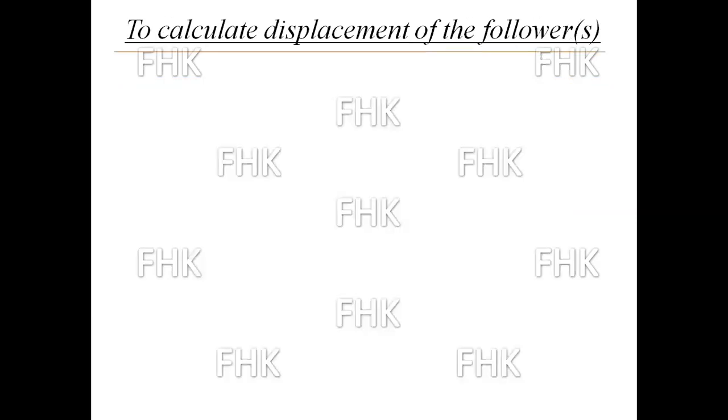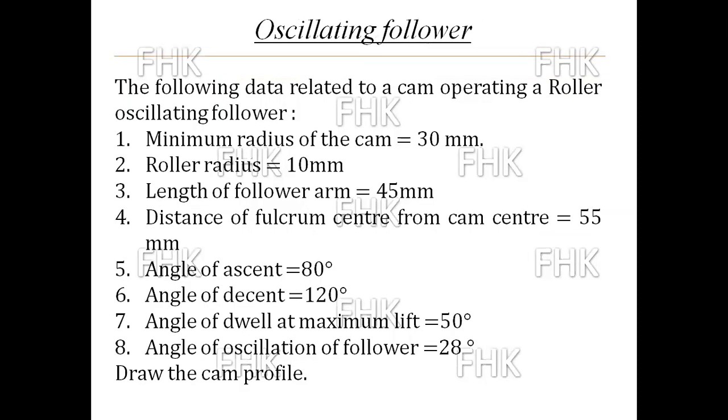Next, the first step for drawing the cam profile is to draw the displacement diagram. For drawing the displacement diagram, first we have to calculate the displacement of the follower, which is not given in the problem statement. As you can see, the displacement of the follower that we have to plot on the y-axis is not given.